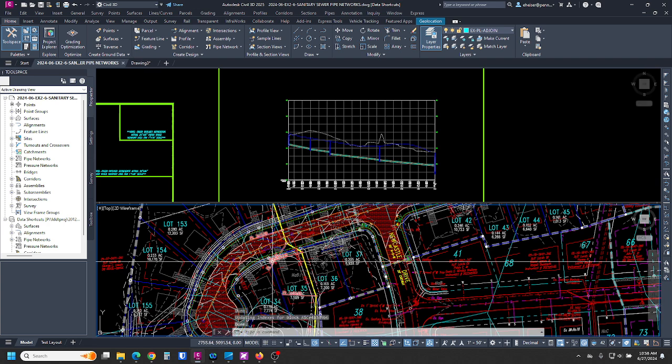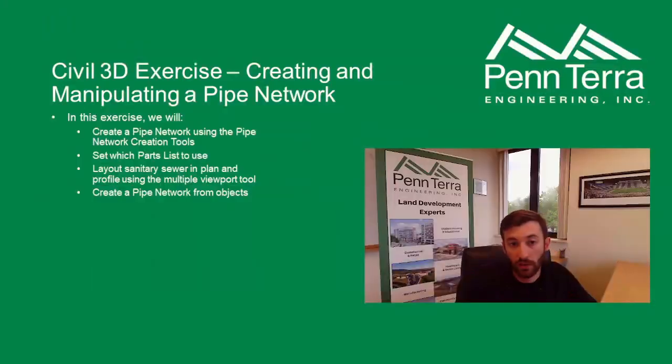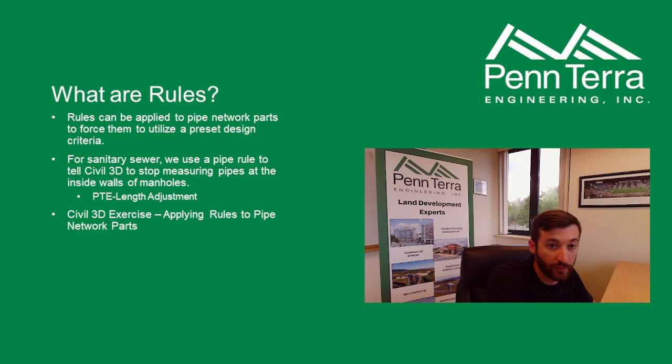So from there, we're going to jump over to the presentation slides. So moving forward from there, rules. Rules are important for sanitary sewers because they set certain criteria for the objects. In this case, Civil 3D doesn't recognize by default that the pipes in a manhole end at the inside walls of a manhole. They assume it goes to the center. So we have a rule that takes care of that. It's called PTE length adjust, and I'm going to show you how we apply it.